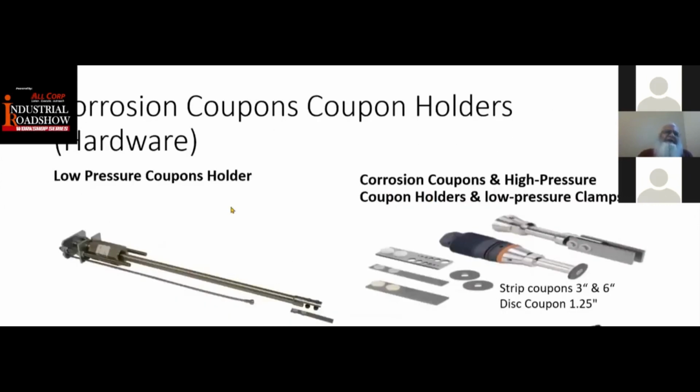Then you can see the corrosion coupon holders. This is a low pressure coupon holder, and these are the high pressure coupon holders and the high pressure coupons. These are the actual devices which are installed right on the pipelines or the vessels, and they can be retracted under pressure, under the actual operating conditions. Same is true with these ones.